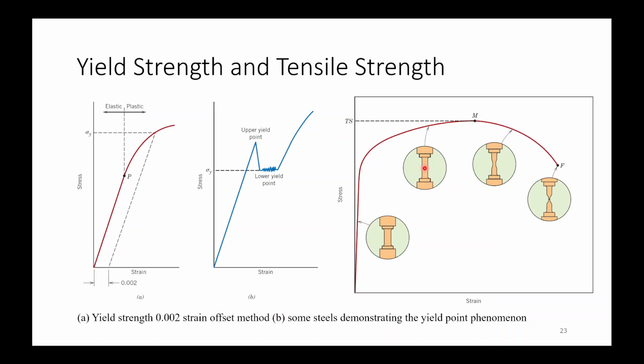Your entire cross section will be uniform, and up to here we'll be seeing necking in this area. Necking is a reduction in cross-section area. After this, your deformation will be restricted to only this necking area, and this material will fail from this necking area. This will be your fracture strength, and this is your ultimate tensile strength.